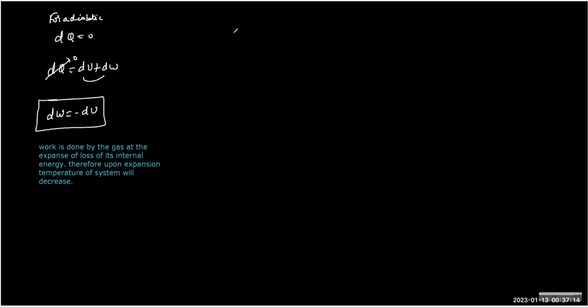So this is called adiabatic expansion. Adiabatic compression is also possible. Again, let's try to plot. Okay, now the question is how to find the work done. How to do the calculation of work done. So it is very simple. Because dU is universal, we can get the answer directly, right? So we can write nCv dT, guys, right? And Cv is R upon gamma minus 1, and dT you can write as T2 minus T1.